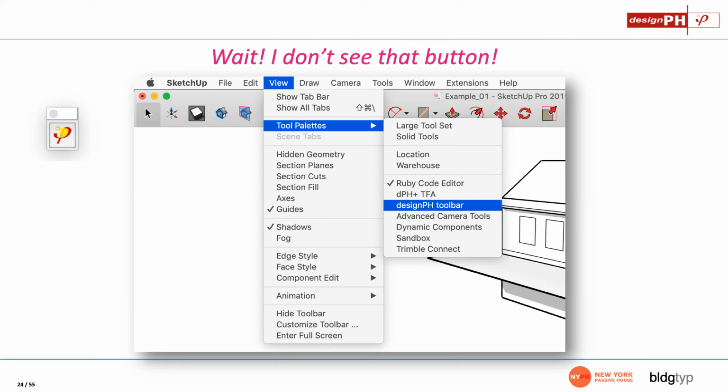And in particular, if you're working in New York City, there are now thermal bridge requirements built into the new version of the energy code that came out in March, and you're going to have to start to calculate psi-values moving forward. So for now, you're going to be able to pull your psi-values from a simplified table, which is built into the code, but probably in the next couple code cycles, you're going to be required to start modeling your own psi-values and building those into your models for code compliance once we're able to do that, things like ComCheck.